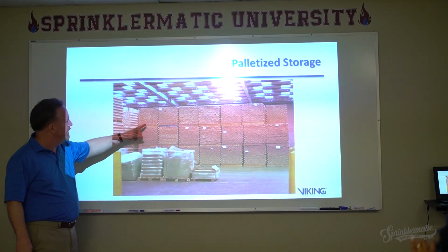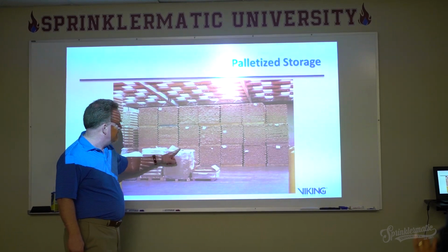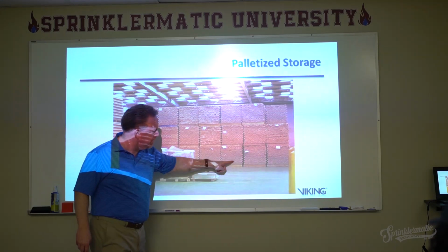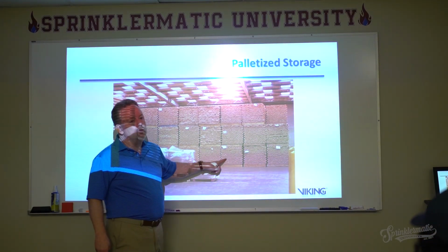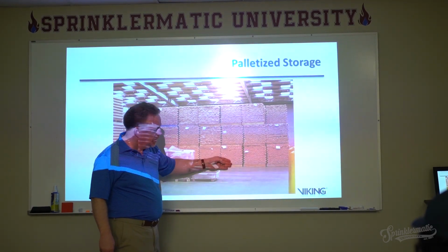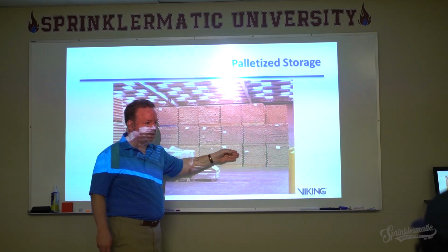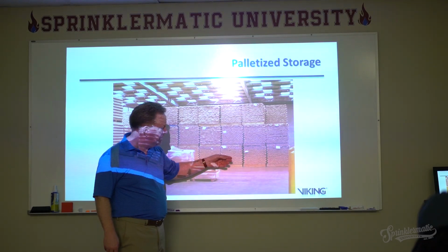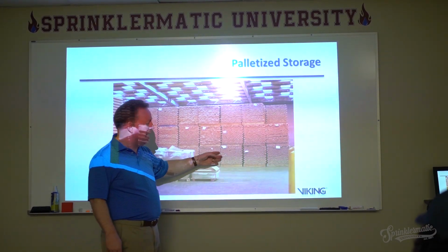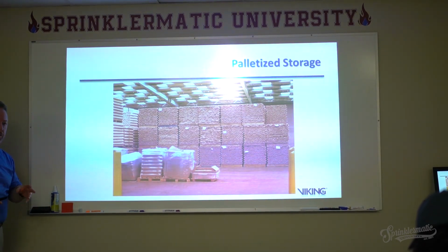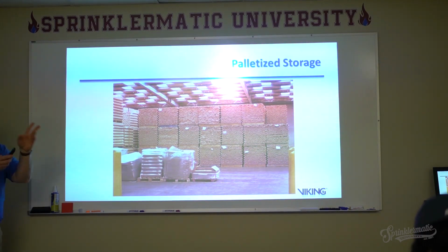And the reason that we look at it that way is because we don't have much space in between here. So if we started a fire out here on this material, it would take a really long time for it to get going, because all it would be burning would be what's on the surface. Okay, very difficult to get it in here. Once it gets in there, it's pretty stubborn, but there's not a lot of oxygen drawing it or allowing it to get in there. Okay, so that's one way of looking at it. That's what we call a closed array storage arrangement. In other words, in a closed array there's not a lot of air that moves around the commodity.